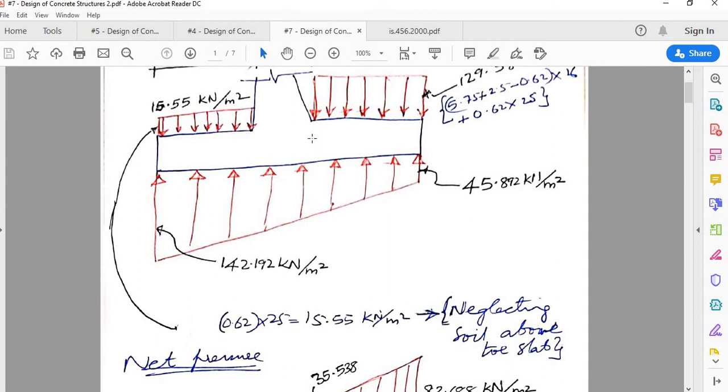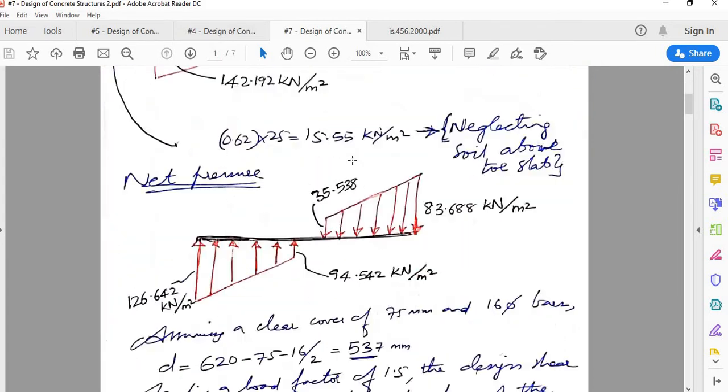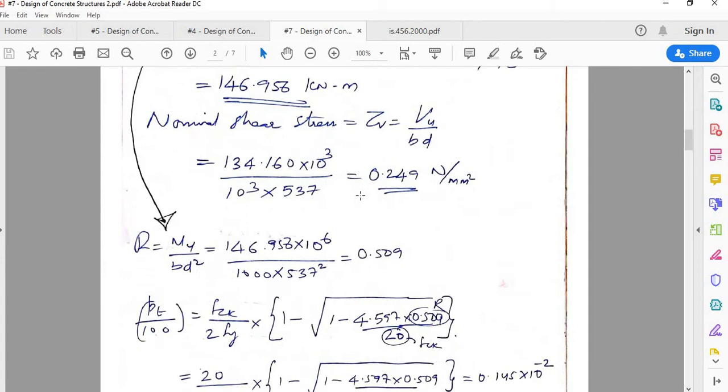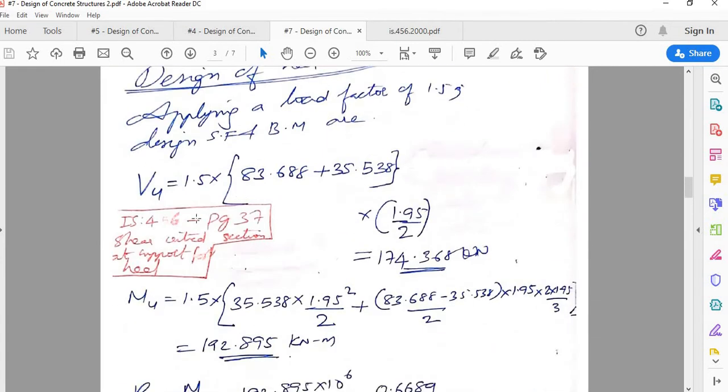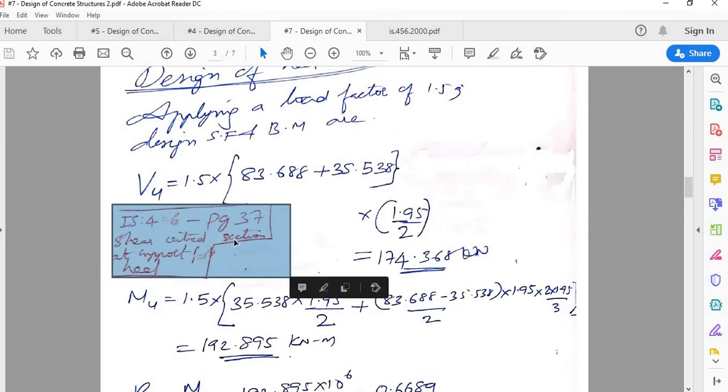Heel slab design is one of the rare cases where the critical section for shear is also at the face of the column or wall. We have discussed that elaborately in the theory, but in case any of you have doubts, you can either go back to the theory lectures or refer to page 37 of IS 456.